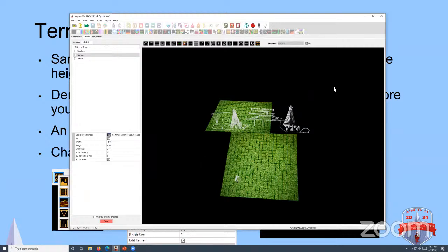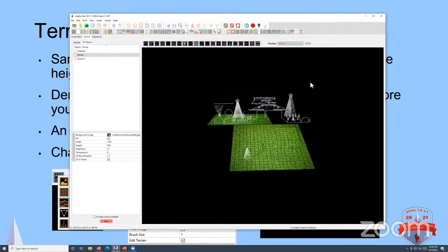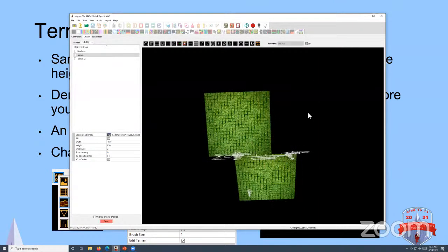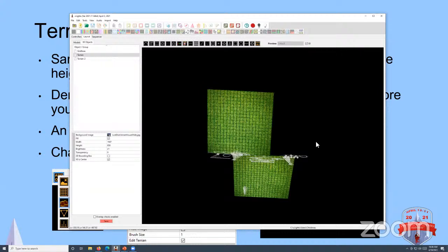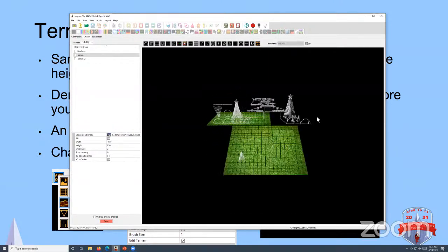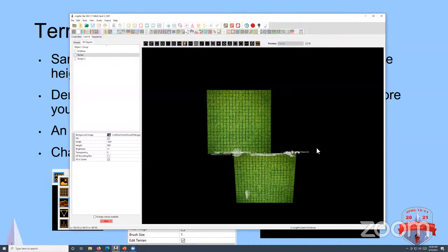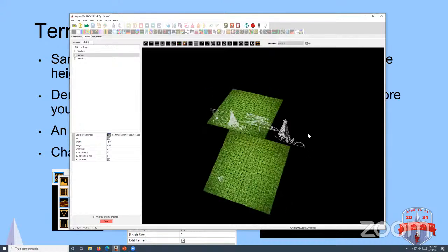What I wouldn't do is rotate my display. Like, oh, my house came in and it was facing down, so I rotate my display 90 degrees and then start placing models. Now all your models are facing the wrong direction, and a 2D renderer is always going to think your models are oriented this way when you actually drew them this way. So that's what someone was talking about. Never rotate your display to match an imported house model. You want to rotate the house model to be oriented correctly in the default display.